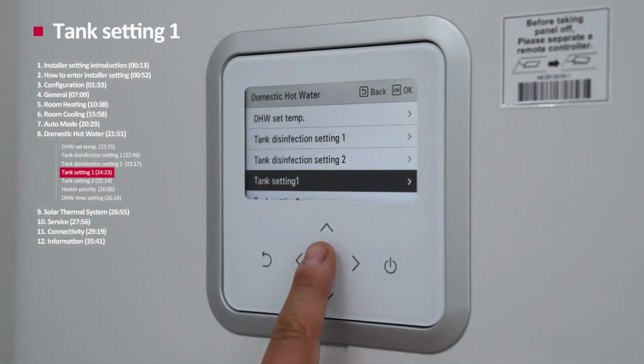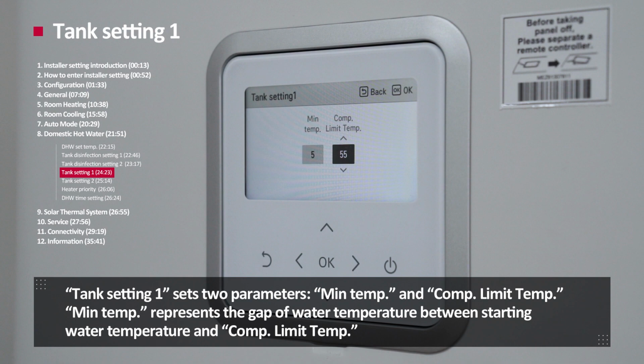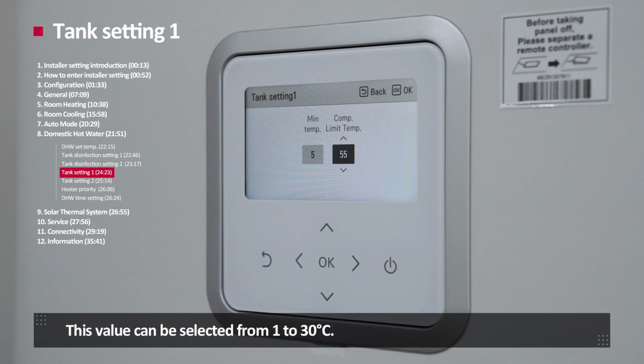Tank setting 1. Tank setting 1 and 2 are for setting up the tank operation condition and for priority setting between space heating and domestic hot water heating. Tank setting 1 sets 2 parameters: minimum temperature and comp limit temperature. Minimum temperature represents the gap of water temperature between starting water temperature and comp limit temperature. This value can be selected from 1 to 30 degrees Celsius.